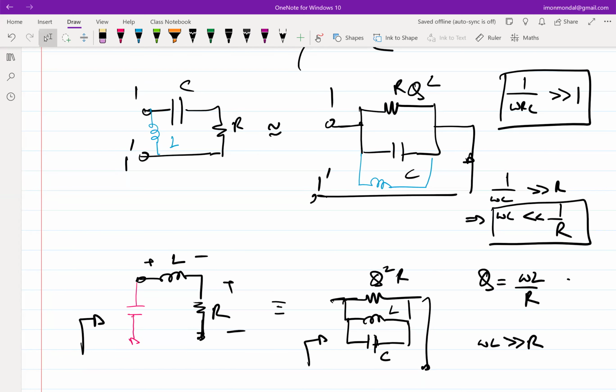Right? So now naturally, based on your design requirement, you can choose which one, because the frequency will be given to you. Very often in RF design, frequency is not a free variable, right? It's given to you. And often R is also given to you because you are transforming that R to something else, right? If you could have changed R, why did you need a matching network? So omega and R are given to you. So all you have to do is play around with the component values. In one case, it seems like it is true for a lower value of omega, right? There is an upper limit. In another case, looks like there is a lower limit of omega, right?